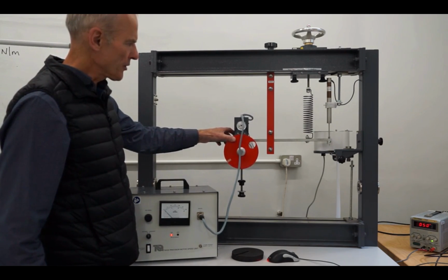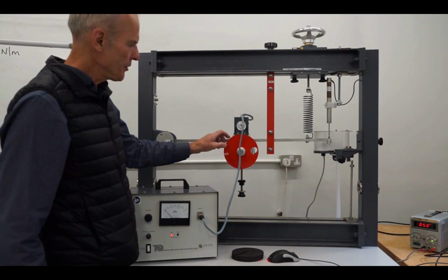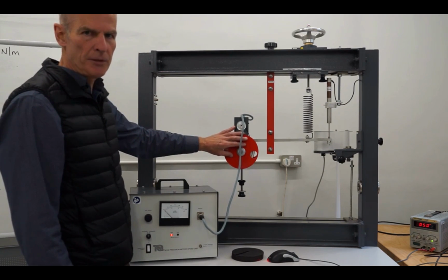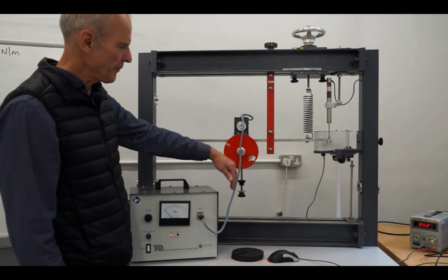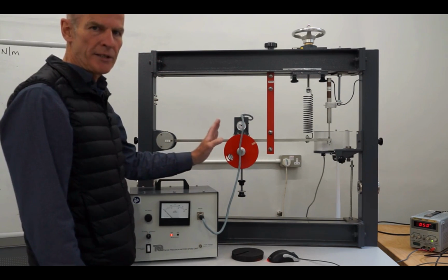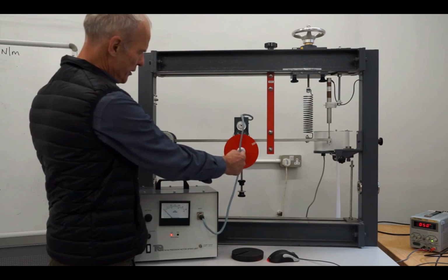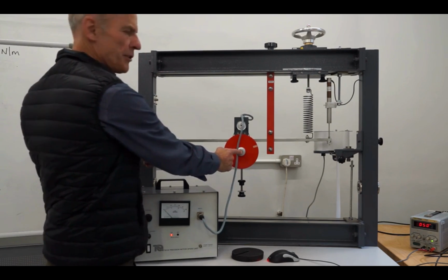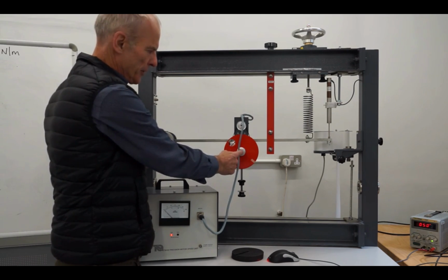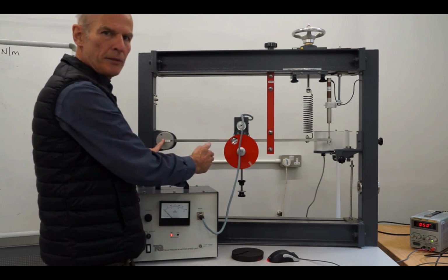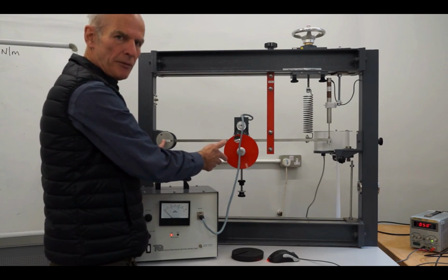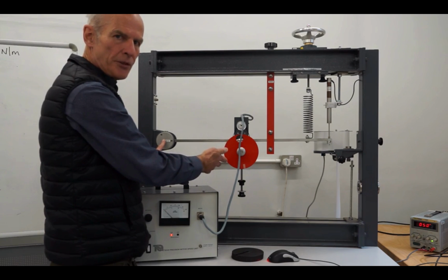Of course, the third experiment will be where we change the position of this mass. Remember, we're talking about moments and not forces. So it's not just the weight of this mass that we add, it's also the position, because it's the weight times the distance. The distance is this distance here, which is L1. If we change that distance, we change the moment exerted, and so we're going to do that as well. We're going to shift this over here somewhere, and again we're going to have to take the natural frequency and then the forcing frequency.